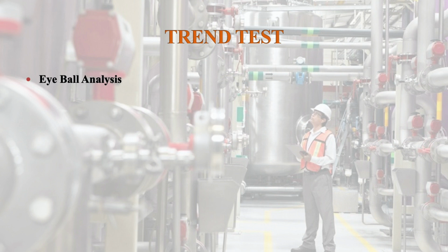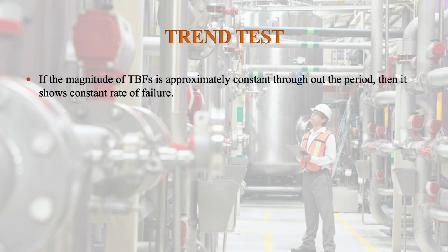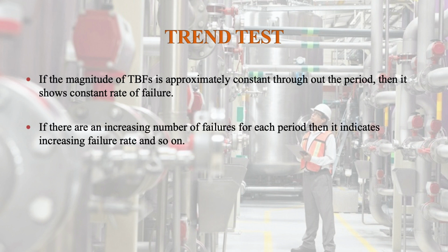The trend test, eyeball analysis. In this we pass our eyes through the chronological times between failures and search for the increase or decrease of the failure rate. That is, if the TBFs are increasing in magnitude towards the end, it shows decreasing failure rate. If the magnitude of TBF is approximately constant throughout the period, then it shows constant rate of failure. If there is an increasing number of failures for each period, then it indicates increasing failure rate, and so on.